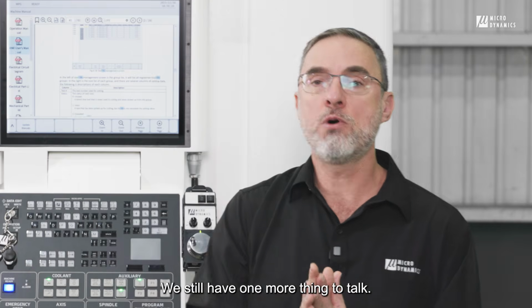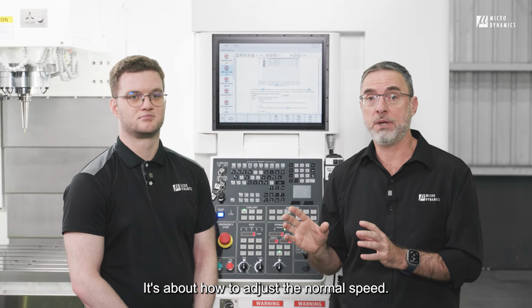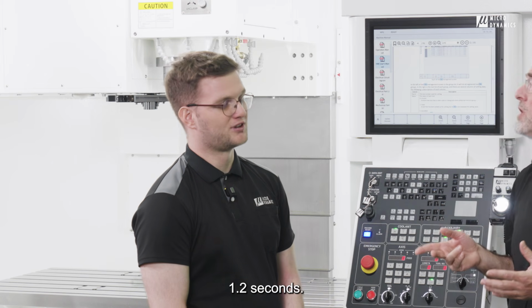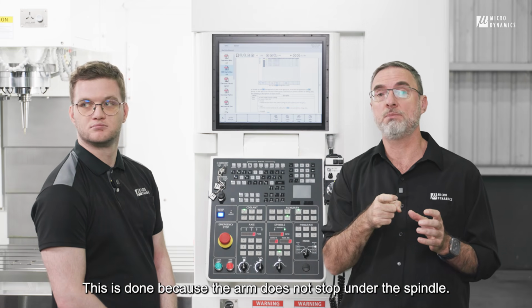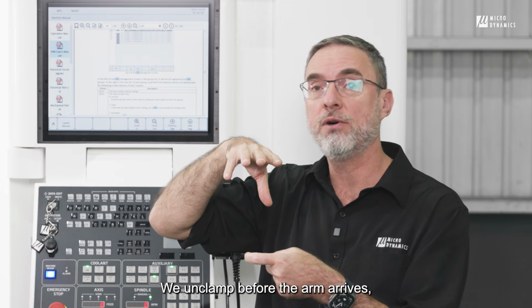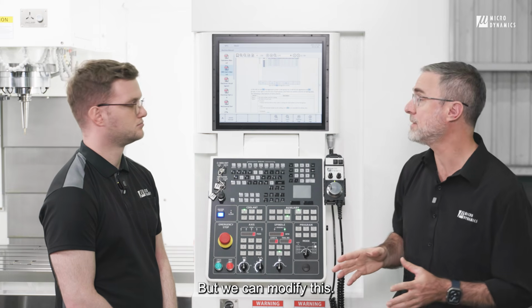We still have one more thing to talk about. It's how to adjust the normal speed. On a Microdynamics standard machine, the tool change is 1.2 seconds. This is done because the arm does not stop under the spindle. We unclamp before the arm arrives, and the motor of the arm doesn't stop. But we can modify this.